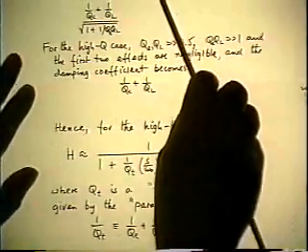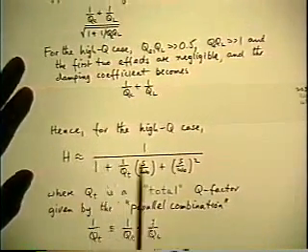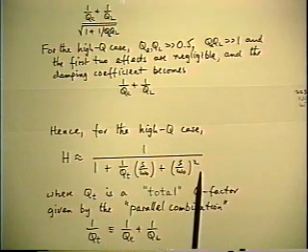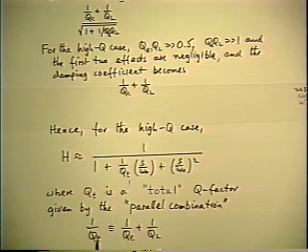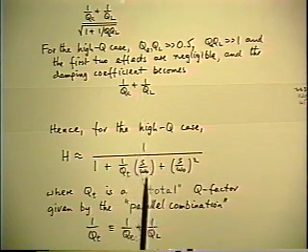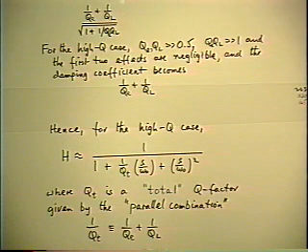So, subject to neglect of these two second-order effects, the voltage transfer function of the loaded filter is the same as the unloaded filter, except it has a total Q factor which is lower than either of the two contributions, and quantitatively is equal to the parallel combination of them. So that's a very simple result. You've reduced it to the simplest possible case, which is useful for practical purposes.